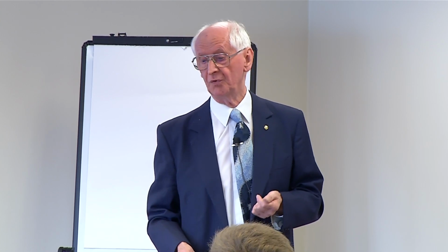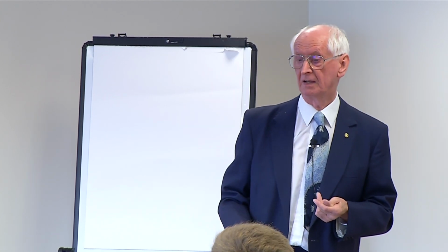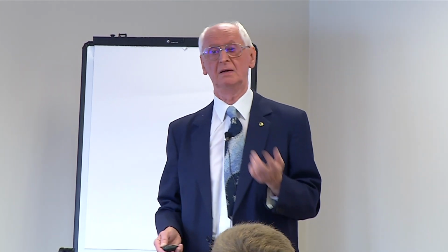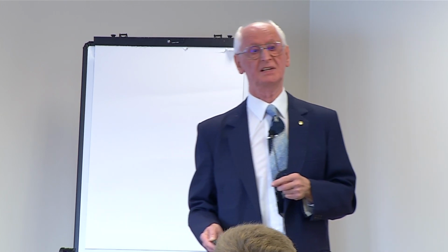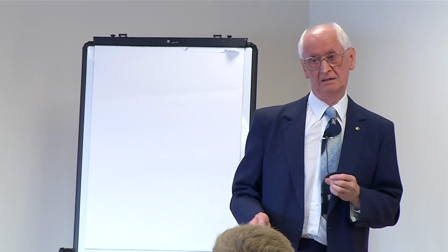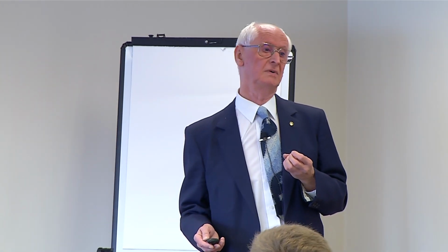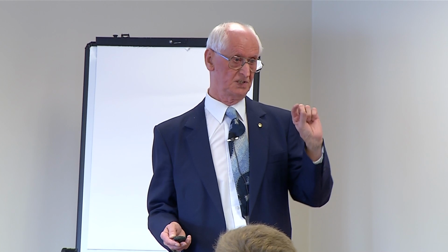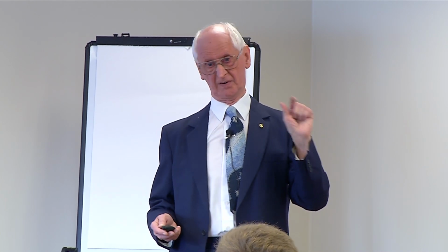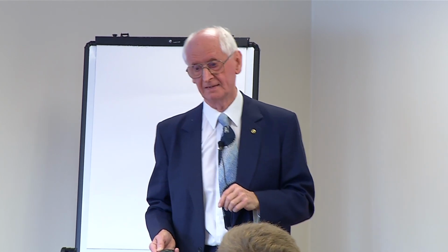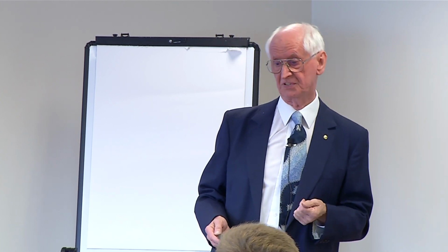It's all right for indoors, but not outside. Truss clips are made the same way, although you can get both in stainless steel now. And the galvanized ones are fixed with 30mm square twisted galvanized nails. Very common, find them everywhere. And the truss clips the same.